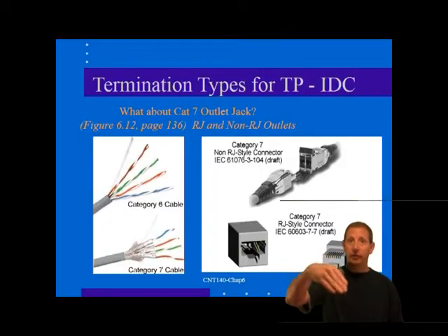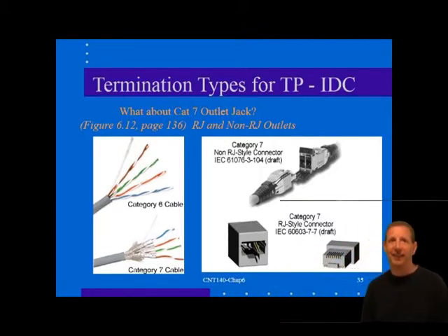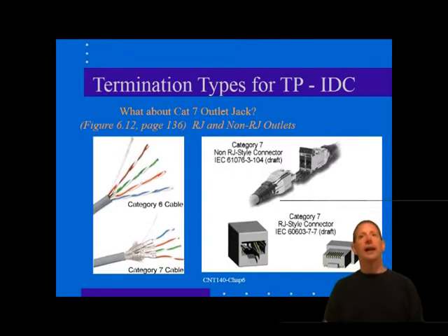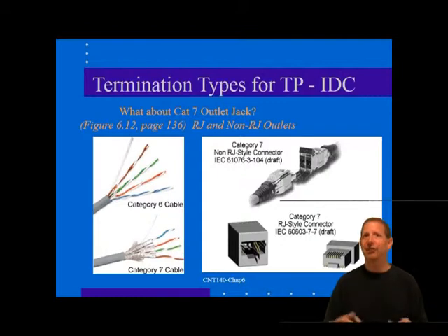So, non-modular jacks for Cat 7. For some time it's been realized and documented that the old reliable RJ45 style of 8-pin modular plug and jack and the crossed-over wiring pattern are the biggest single contributors to the limitation of copper link performance. Old reliable causes crosstalk, return loss problems, shielding issues, EMI, and is generally a pain to assemble.